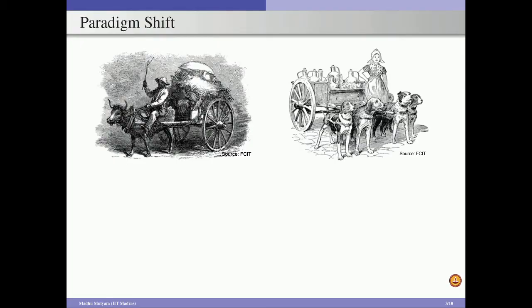This shows that rather than considering a complex superscalar processor with aggressive superscalar techniques and deeper pipelines to get our computation done quickly, we can consider a collection of simple cores, all working in parallel, so that our computation can be finished quickly, and we can also reduce our overall power consumption and minimize the design complexity. As a result, the overall performance improves at the same time without increasing the amount of power consumed for the computation.